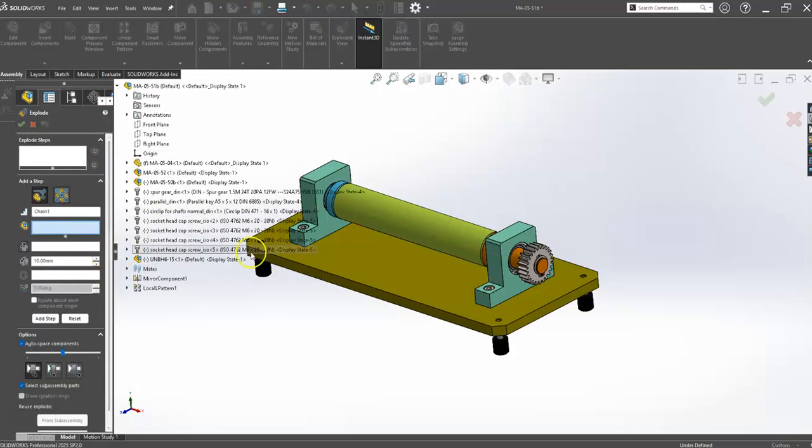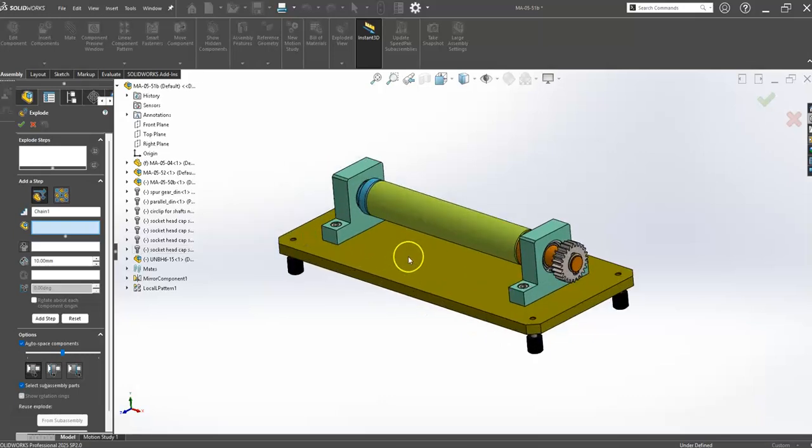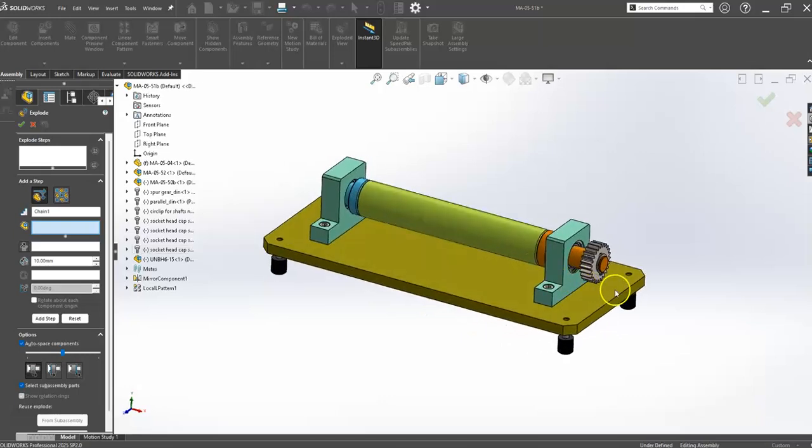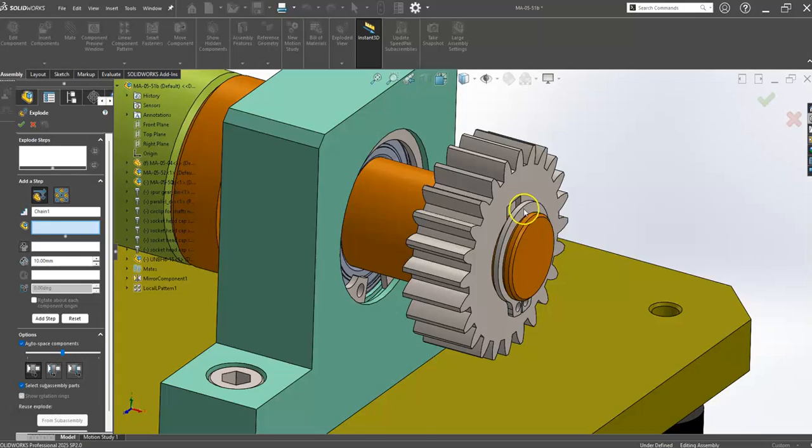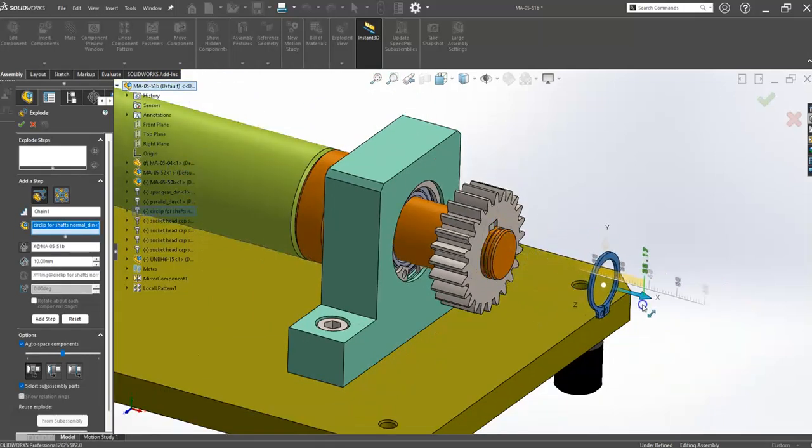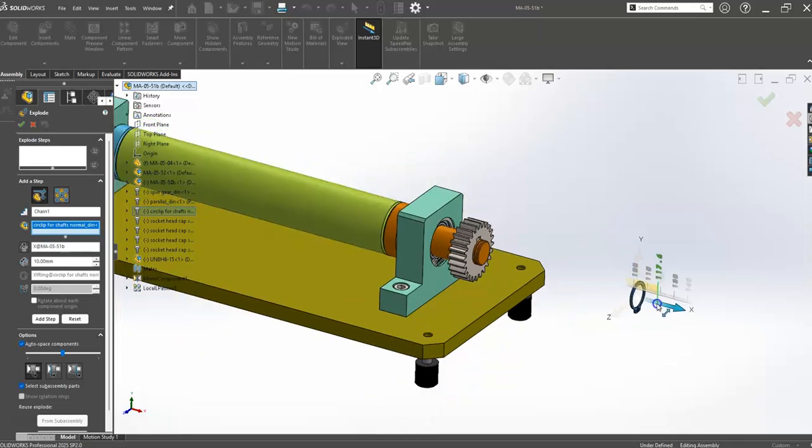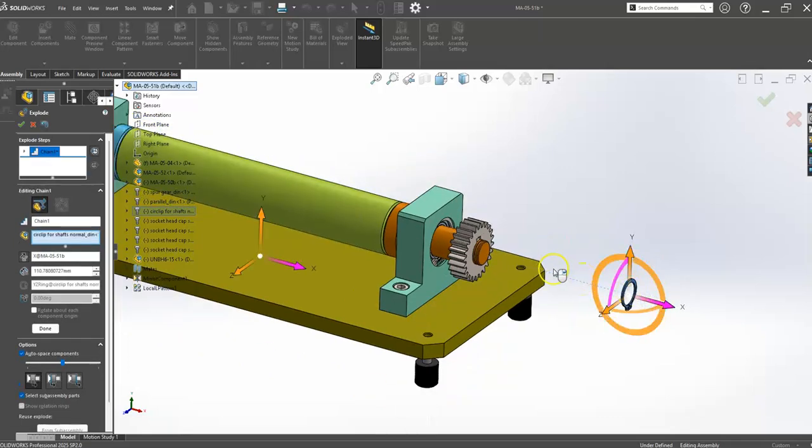When the exploded view options come up, we'll try to disassemble the assembly in the way that it was created, nearly as such. So what makes practical sense. So we start with the clip and we can drag it along that x-axis. We can roll the mouse at the same time and place it out there. When you're happy roughly where it is, you can write in an exact distance here, or usually you're good to go with the distance you've dragged it. You just have to hit select done.